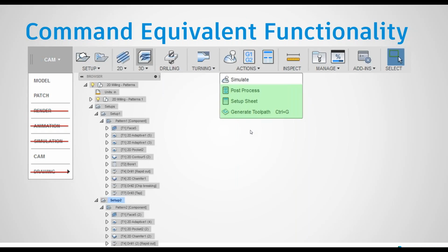There are some workflows that this is nice for. If I've created a model and I have a toolpath on it, and now I automate modifying that model, then I can also automate updating the toolpaths and post-processing with those new toolpaths. But what I can't automate is creating new toolpaths. That should be coming at some point in the future, but it's not here now.